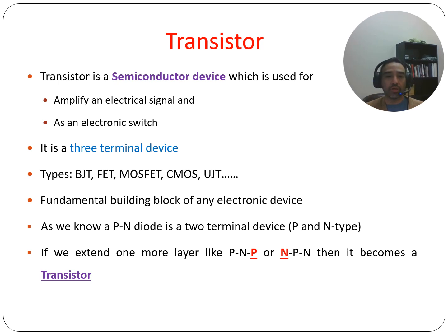It uses this oxide layer to insulate the gate from the channel. And so what this does, it allows for high input impedance and very low power consumption. A key feature for the MOSFET is the gate that's insulated. Again, it just helps in high speed switching, low power consumption applications.